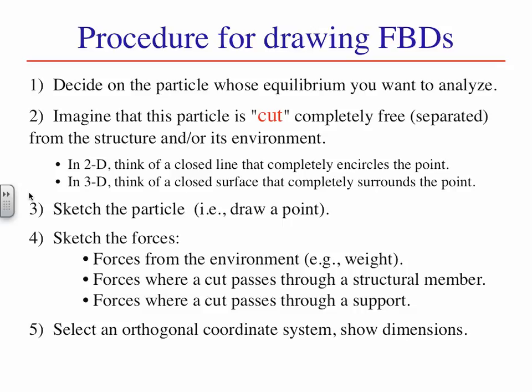Second, imagine that the particle is cut completely free from its surroundings. This process of separating or isolating the particle is what puts the free in free body diagram. It may be helpful to draw a closed line around the particle of interest. This enveloping contour could be as simple as a circle, but it need not be this simple. The important feature is that it be a closed, non-self-intersecting path. No figure eights or other overlapping lines.